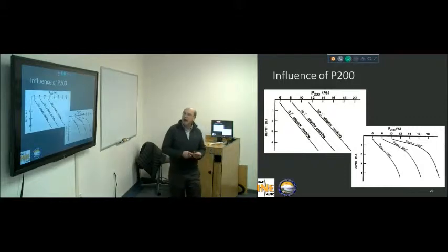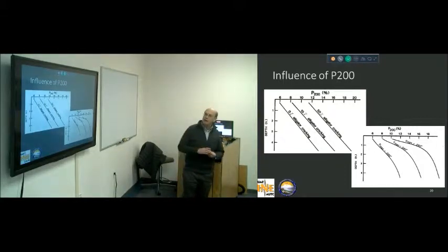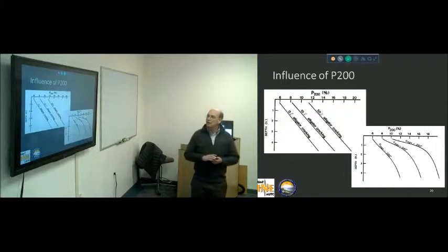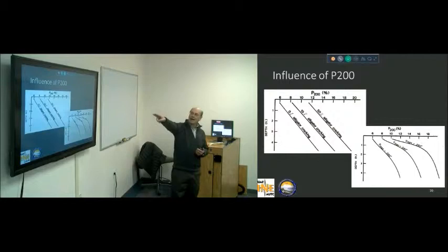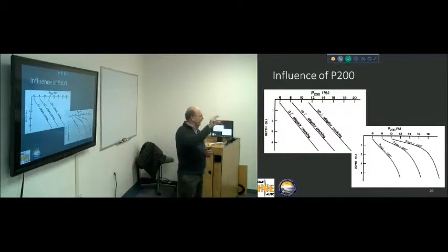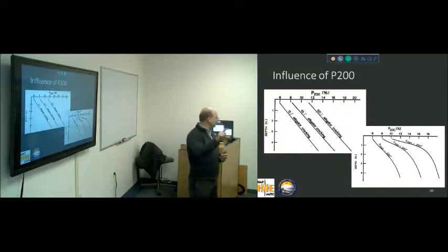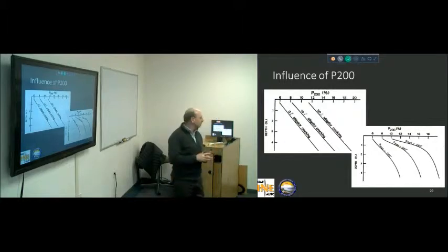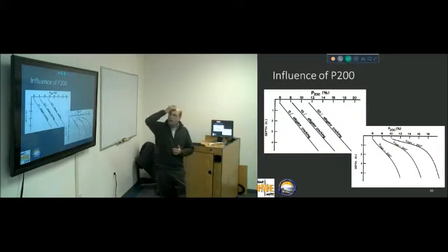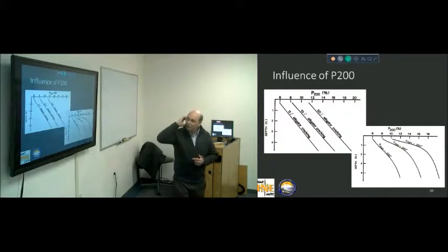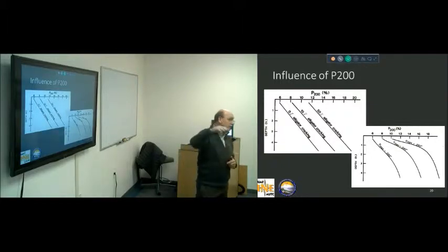Okay, here's a graphic of that. As you can see in the graphic on the left, as you increase the 200 sieve, you also get an increase in fatigue cracking, alligator cracking. But what's important to note here is that the slope of that line indicates that as you get deeper, you can allow the fines content to increase. That goes back to what we said earlier: because the load at depth is less, we can allow that material to be weaker, and so we can allow more fines content without adversely affecting the design life of our pavement surface.